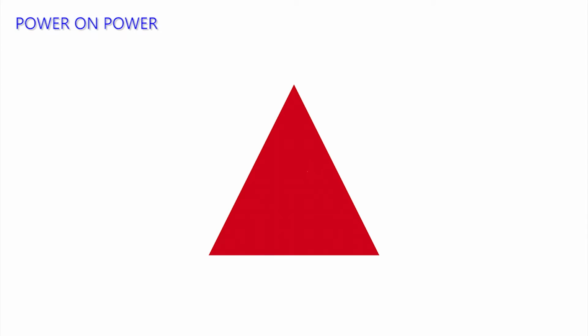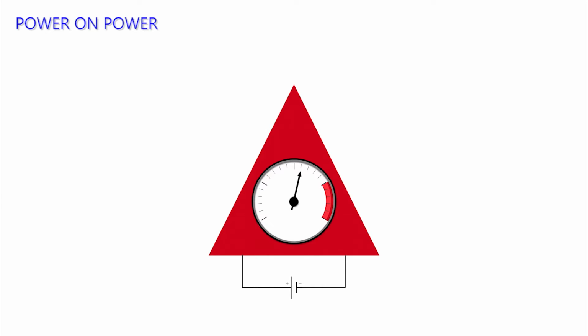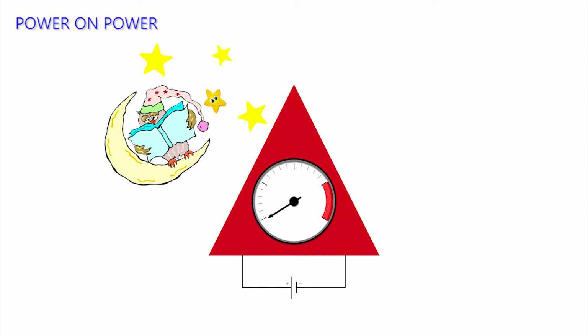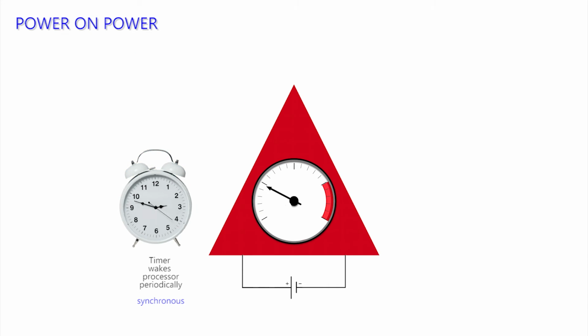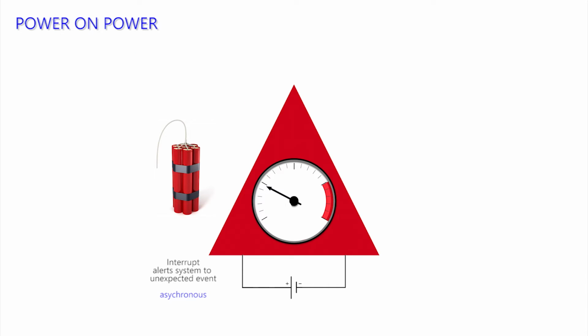As many devices are often remote, they also tend to be battery or solar powered. There is, therefore, a need to reduce power consumption. The power requirements of a thing may be reduced by running the processor at a low speed. A second method is to cause the whole unit to sleep. To be useful, the device has to awaken periodically to reconfirm its status, or be able to be awoken quickly and respond to any unexpected change in state. We will see how this state of hibernation affects how things are treated later.